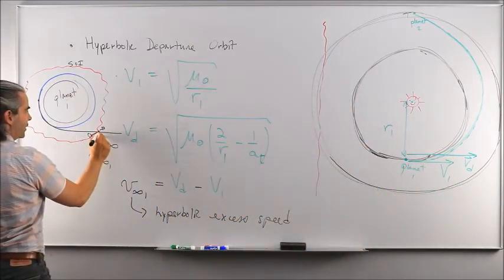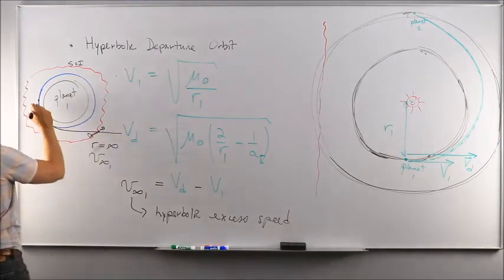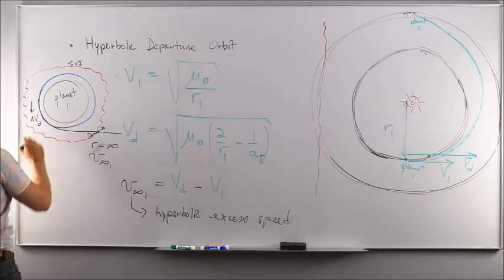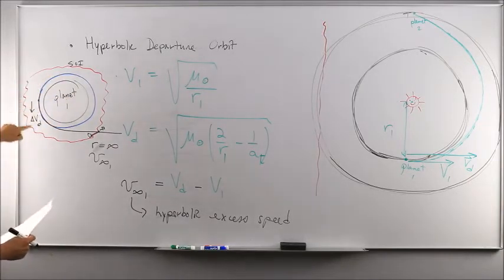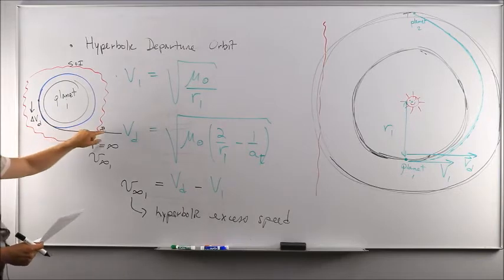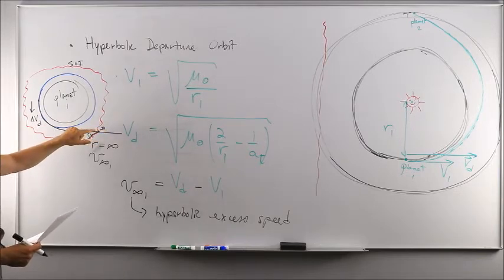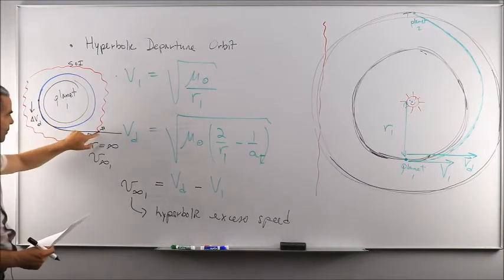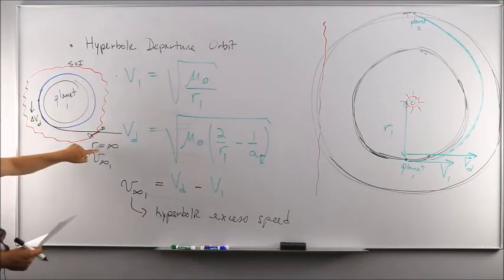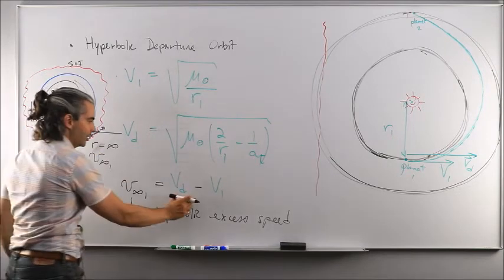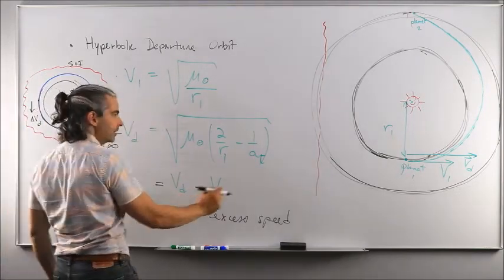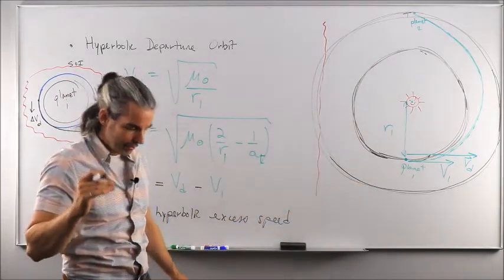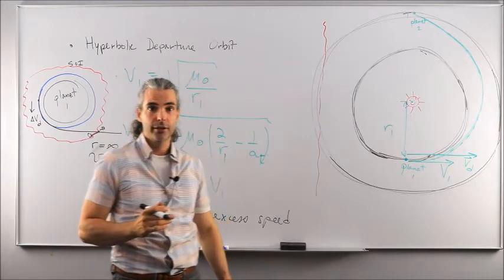The delta V maneuver is not applied here, but actually the only delta V maneuver in the entire system is delta V departure that takes us from the circular orbit up to a hyperbolic orbit that will be sized such that the speed the spacecraft would have along this hyperbolic orbit whenever r reaches infinity exactly matches the difference in heliocentric speeds calculated from this perspective. And that is the key thing to analyze interplanetary flight, okay?